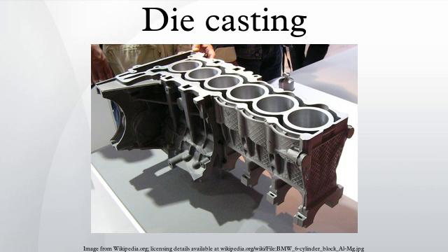Most die casters perform other secondary operations to produce features not readily castable, such as tapping a hole, polishing, plating, buffing, or painting. Inspection: after the shakeout of the casting it is inspected for defects.